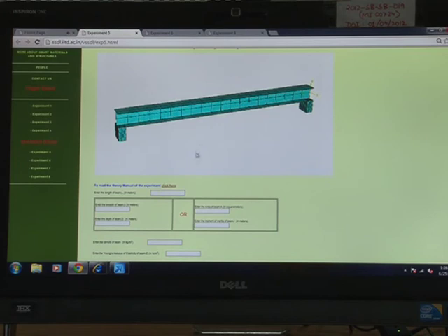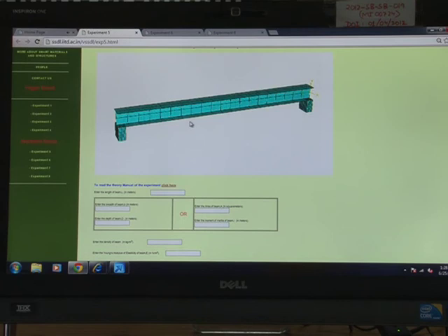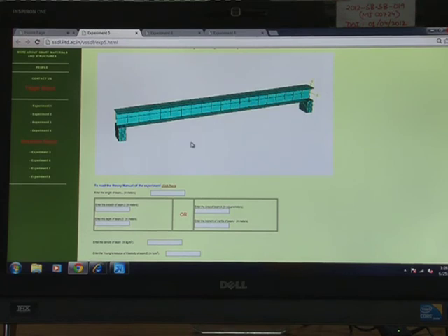For this case, the simply supported beam was excited into a flexural mode, which resulted in alternating compressive and tensile strain at the top and bottom faces simultaneously. The main objective of this experiment is to study the modes of vibration for the simply supported beam under flexure. And the total model is based on the discrete system, where the user can easily get the natural frequency of the beam and simulate the first few mode shapes.